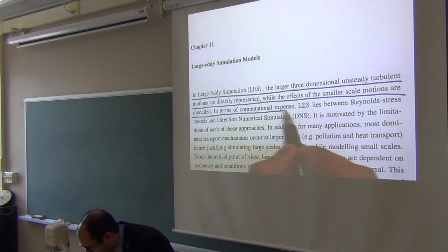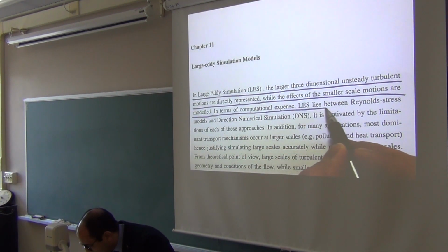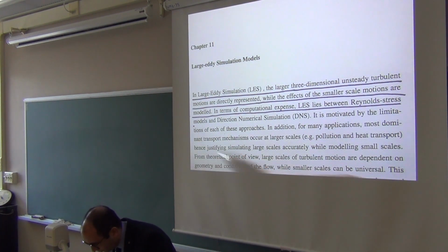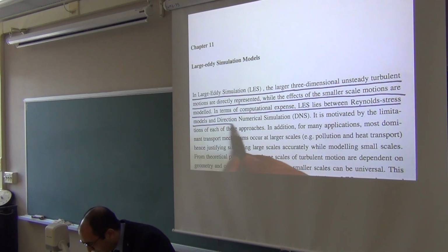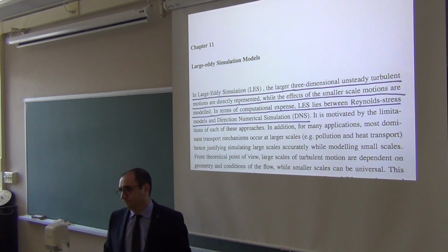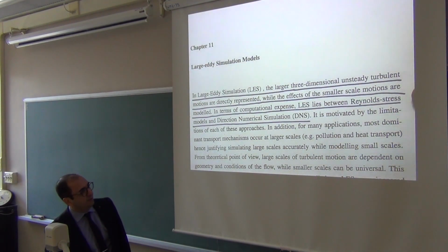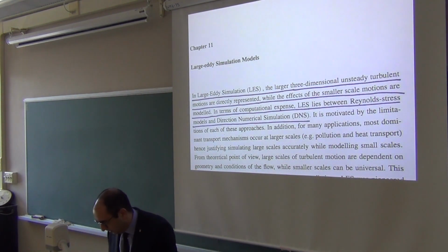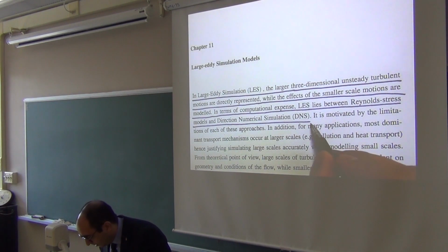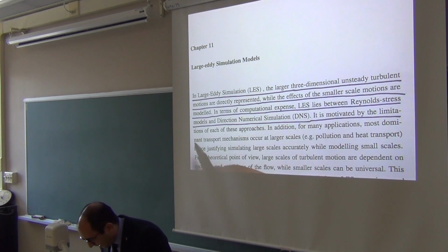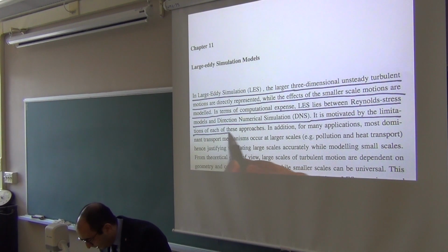In terms of computational expense, we already said that LES, large-eddy simulation, lies somewhere in between Reynolds stress models or turbulent viscosity models and direct numerical simulations. So it's neither too easy nor too difficult from the point of view of computational expense. It is motivated, in fact, by limitations of each approach.